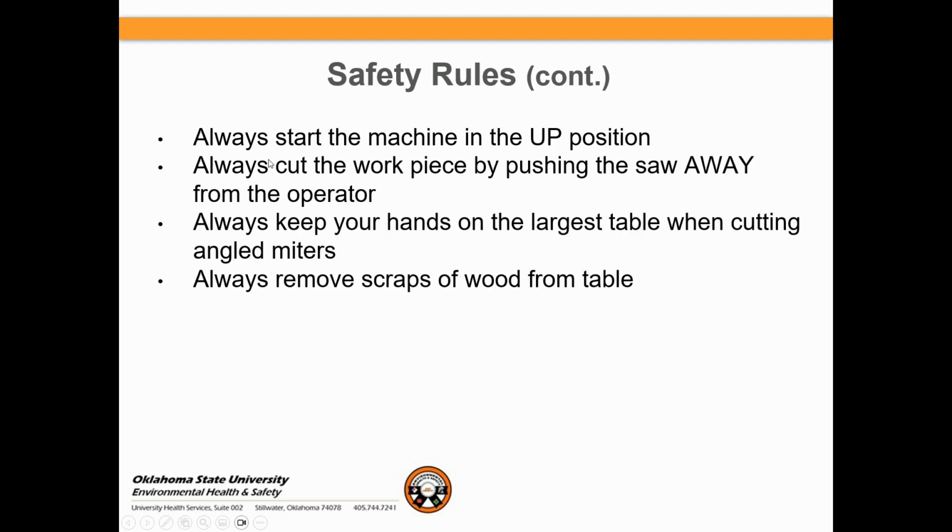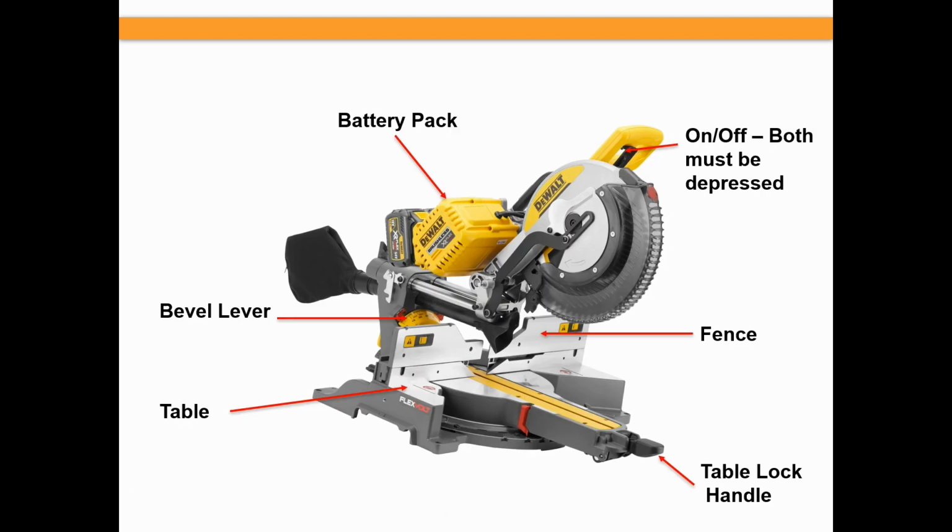Always start the machine in the up position. Always cut the workpiece by pushing the saw away from the operator. Always keep your hands on the largest table when cutting angled miters. And the other thing too is always remove scraps of wood from the table.